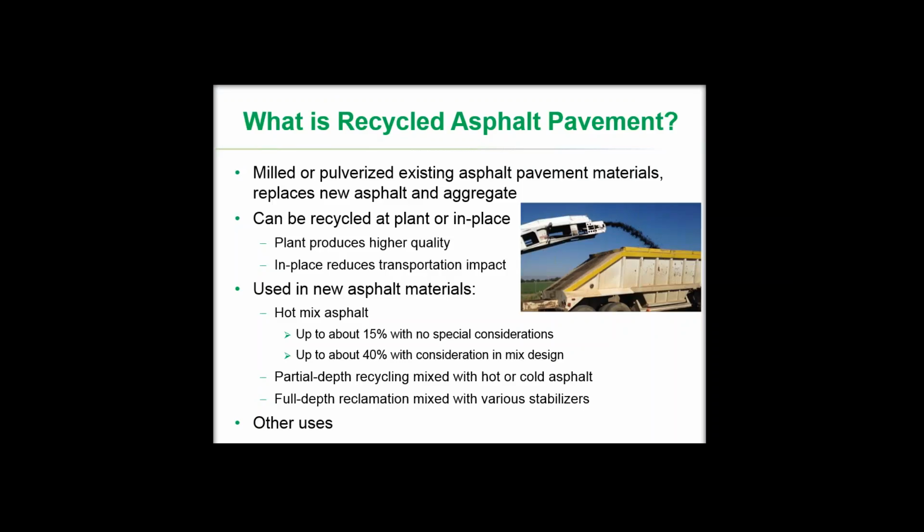Plant recycling produces higher quality and more consistency. In place recycling reduces the transportation impact. So those are two things to consider on whether to recycle at the plant, haul it to the plant and recycle it, or recycle it in place.